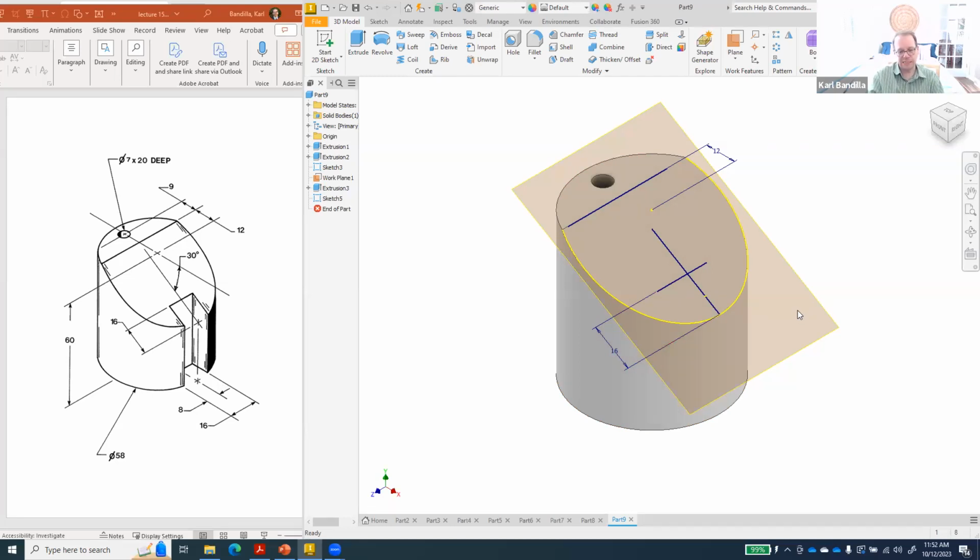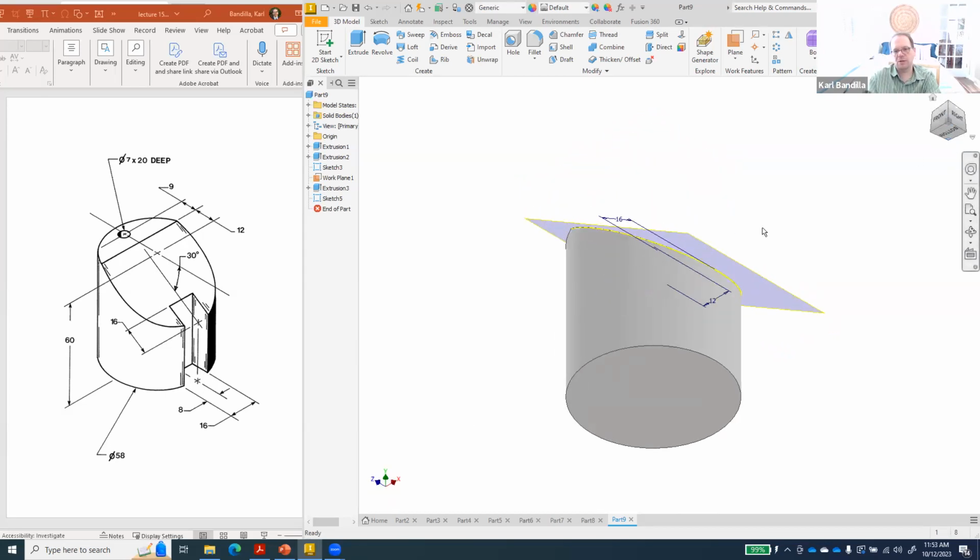Now, some of this you will see take a whole bunch of steps in between to get to where we want to be. And one thing that I would highly discourage is, of course, that if we know what this length is, we know what that angle is, we can figure out what this length has to be. But I would strongly recommend against that, because anything else that you change, that number is not going to change when you move stuff around. So I would not do that. I would try to construct stuff as much as possible.